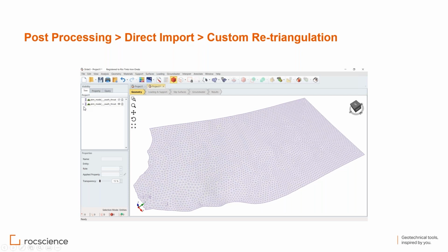So that's the difference. If you do the repair in the post-processing, no history is going to be left. So it's going to be a fresh surface being imported to the software, so you can't see the original surface. But if you bring the surface in the software and do the repair, this arrow shows the history, so you have access to the original surface.